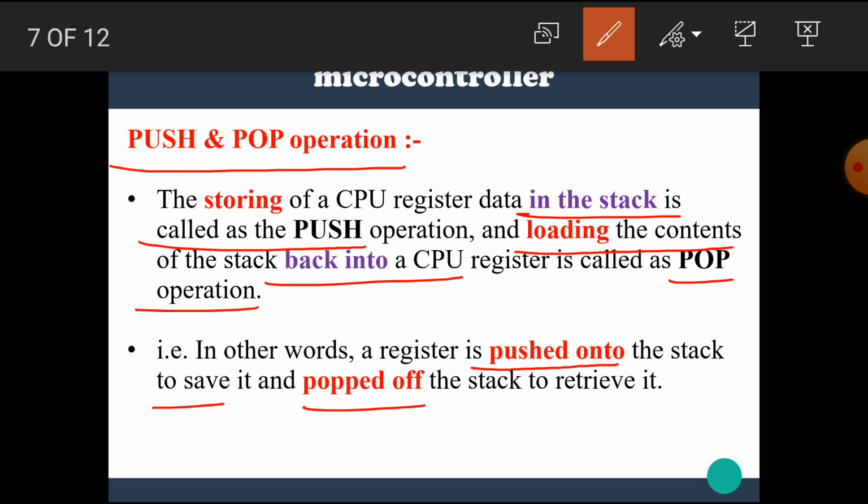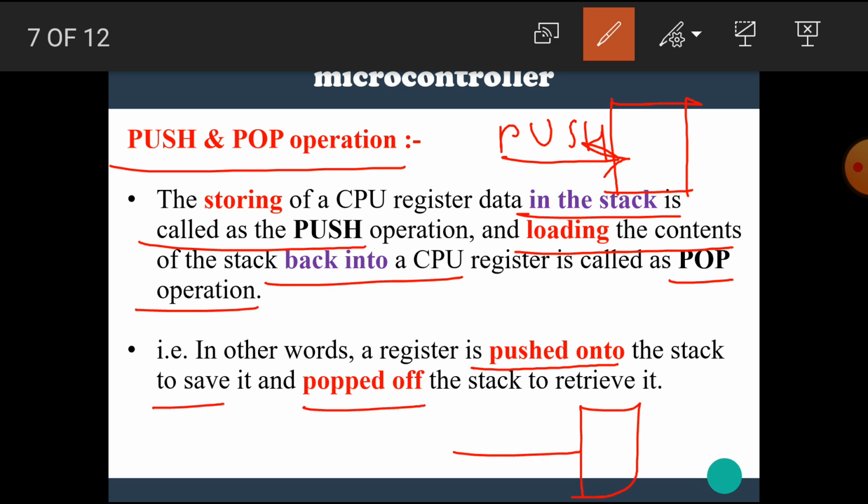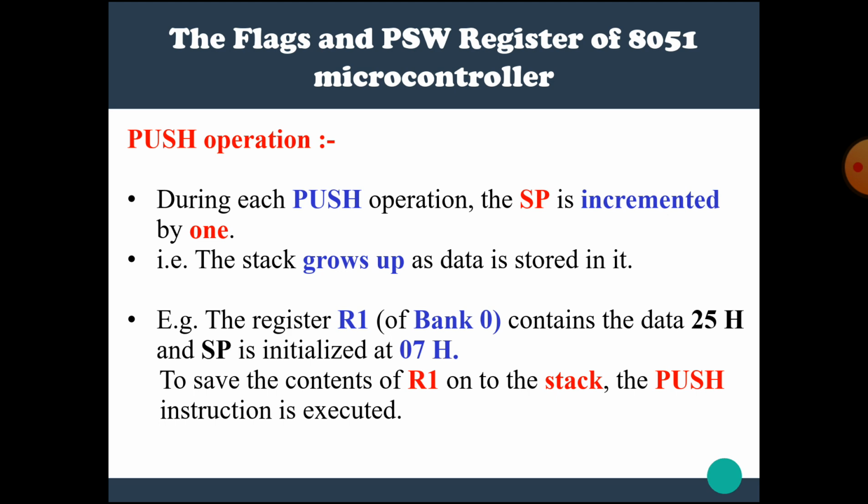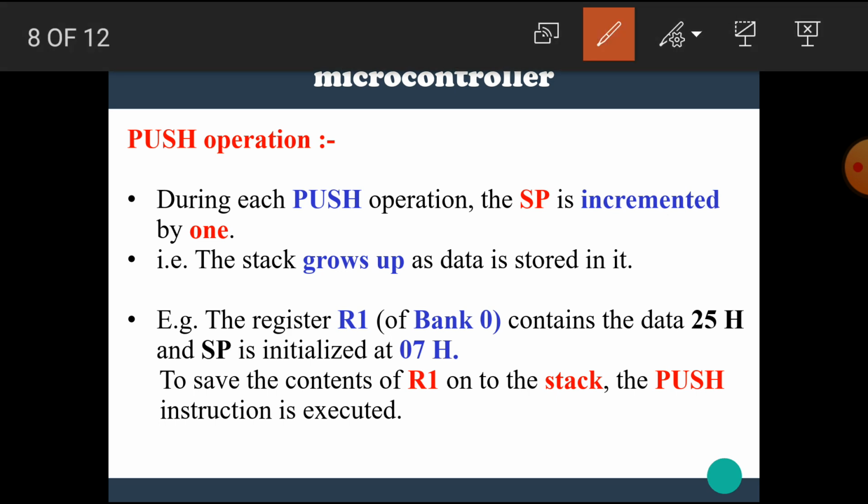to retrieve it. We can also say that if this is a stack area and we save the contents into the stack, then a push operation is performed, and if the data is taken out from the stack, then the pop instruction is required. Let's see the details about each push operation and pop operation. First, let's see the push operation.